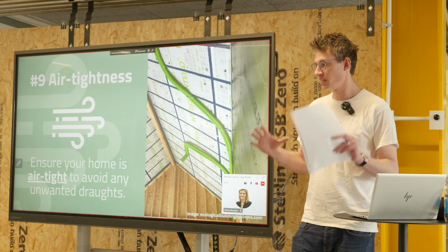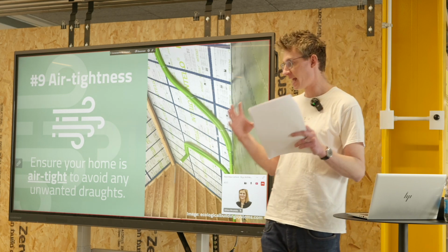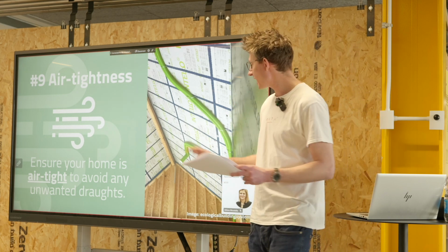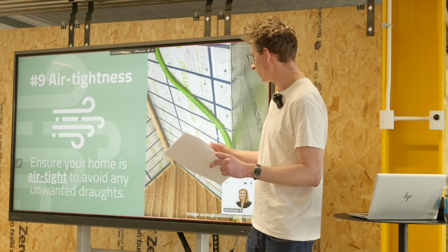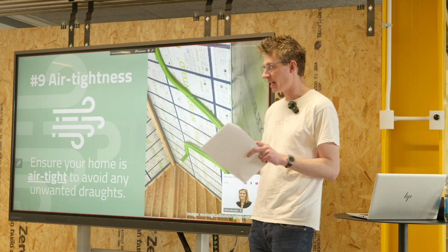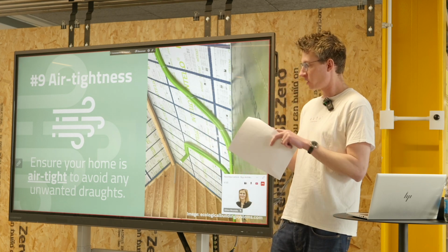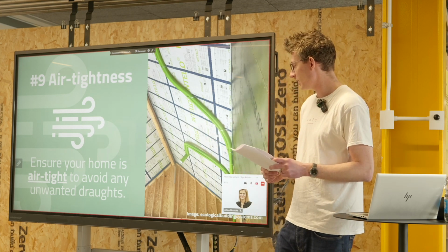A bit like the insulation, you've got a thermal jacket and you want an airtight jacket as well. The airtight membranes are then taped into the windows. Any penetrations, you want to avoid obviously any penetrations coming through that, but any penetrations have got special grommets and special tapes to seal it off.